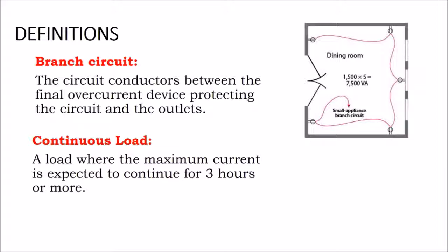So what does that mean? Well, we have electrical appliances in our home that work all day, and then we have electrical appliances that we only use for 20 minutes at most a day, like your microwave. And so that gets into a difference between continuous and non-continuous loads. So the question is, well, what would a solar array be? What would a wind turbine be? Do we size it as a continuous load or a non-continuous load?